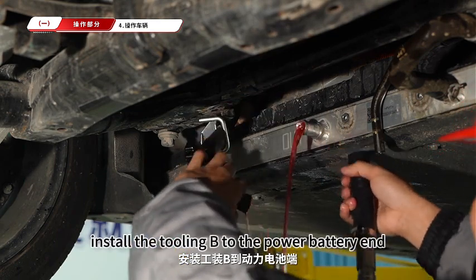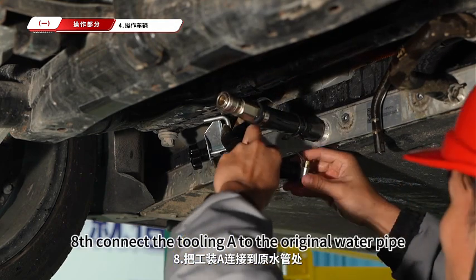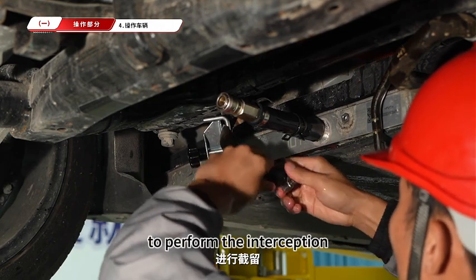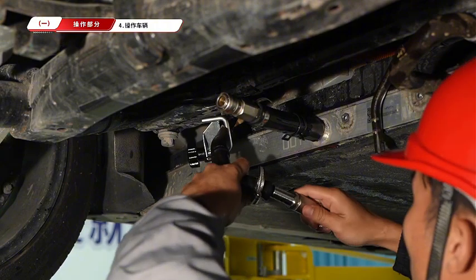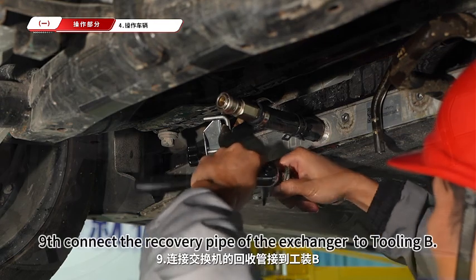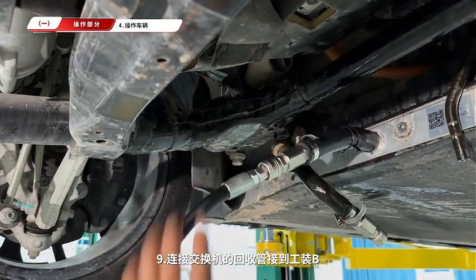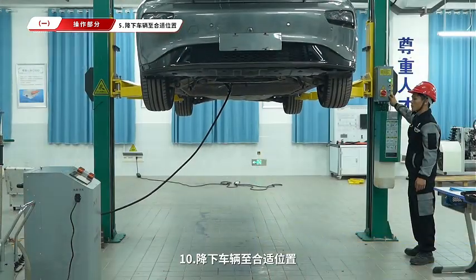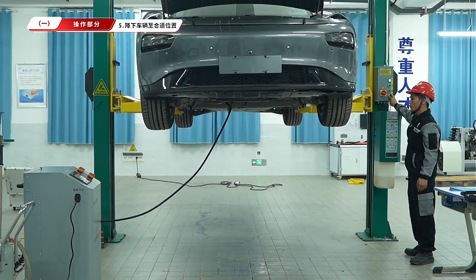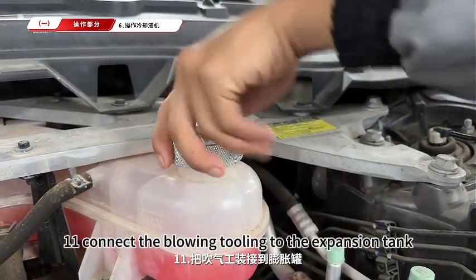Install the tooling B to the power battery end. Eighth, connect the tooling A to the original water pipe to perform the interception. Ninth, connect the recovery pipe of the exchanger to tooling B. Tenth, lower the vehicle to the appropriate position. Eleventh, connect the blowing tooling to the expansion tank.